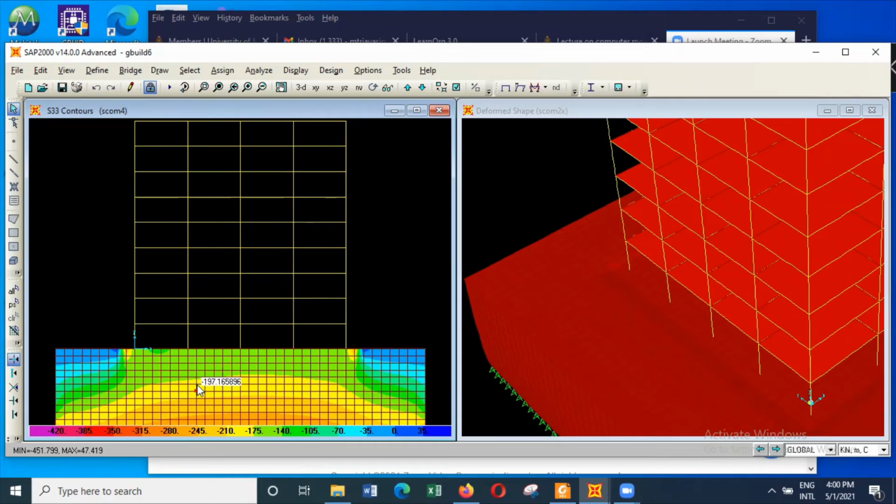But as you go down, it will start increasing, because then the weight of the soil will also start acting. So in this area, you get some dispersion of the stresses, because due to the presence of the raft there will be a dispersion of stresses. Because of the dispersion, the density contribution will be less. But as you go down, you will see the density of the soil can contribute more, and it increases. So you expect the stresses in this area to be higher, because the weight of the soil will also be contributing.